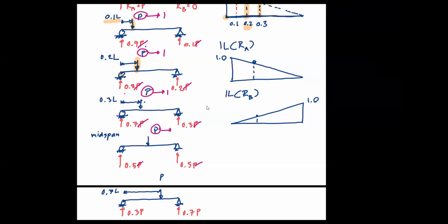We construct the influence line by plotting the values of the design functions. Now the design functions would mean the reaction of your structure, the internal shear force anywhere, or the internal moment anywhere. Now these design functions will change their values when we move the load around. So when we move the load around and the design function changes the values, we plot those values with the location of the load that we move around. The results of that is something we call the influence line.